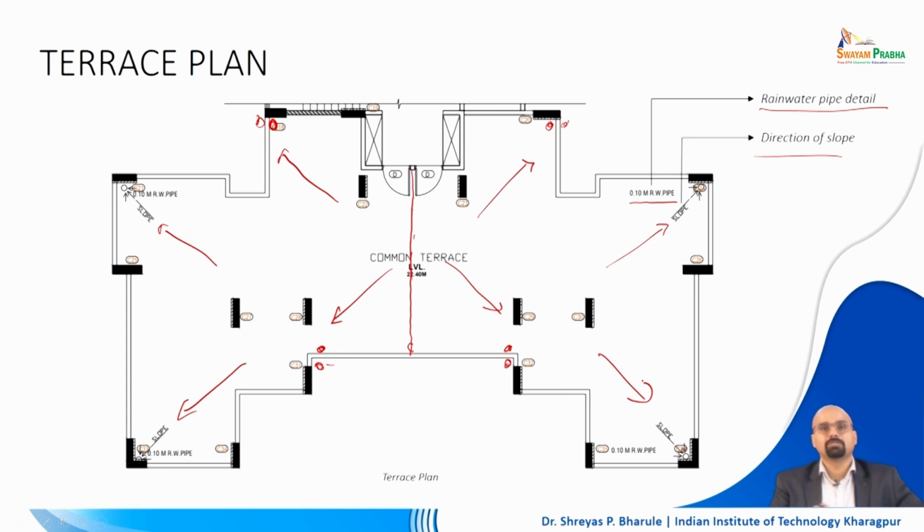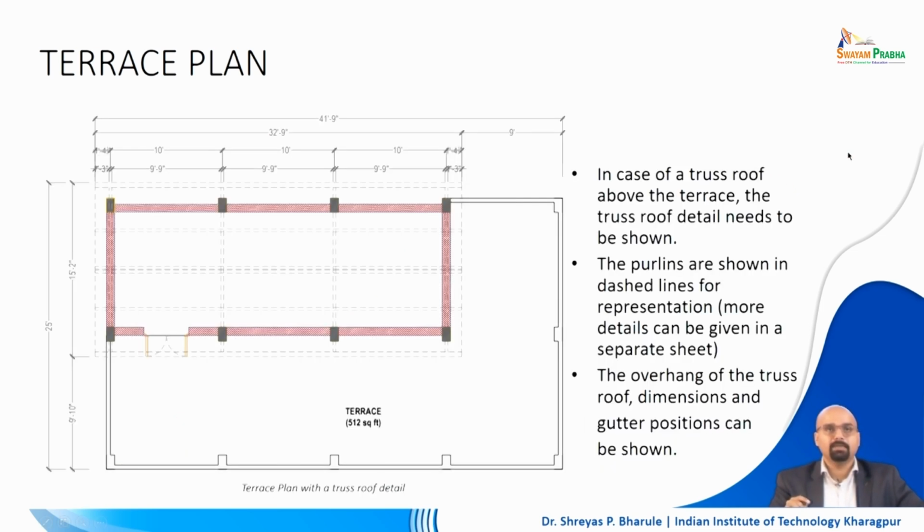So, this is how the distribution of water would happen with a very low level ridge, line, and then you create simple slopes, rolling slopes, so that water rolls out with its own weight and gravity, right. So, that is how you drain out a terrace. Okay, very important, and to be considered for all the different drawings and all the different structures that you do of a terrace plan, right.